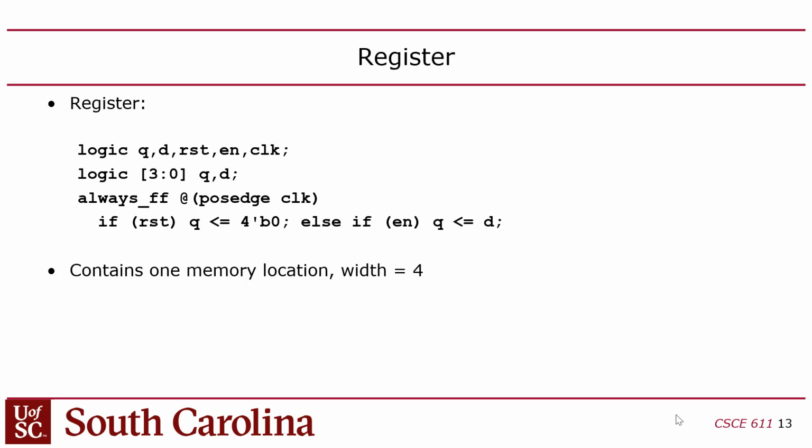So the case for the enable is, in our CPU, we need a way to get output out of the CPU and display it on the hex displays on the board. So you're going to have a register in your CPU that's going to hold whatever value is being outputted on the 7-segment displays. Right now in lab 2, you just had a connection directly from the switches into the 7-segment displays. Now the displays themselves will be driven by your 7-segment decoders, but the input to the decoders will come from a 32-bit register inside your CPU, which will have to have an enable on it because you want to hold that value and only change it when you execute the CSRRW instruction that updates the output. Do you guys follow that? Does that make sense?